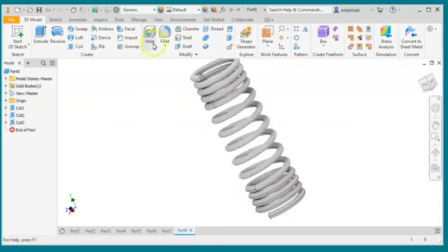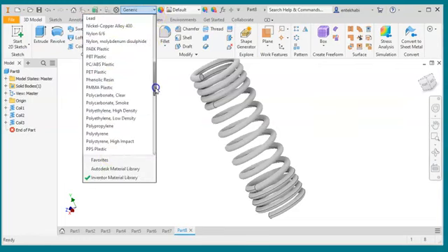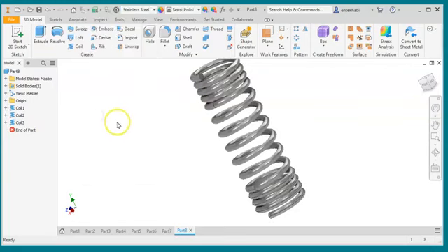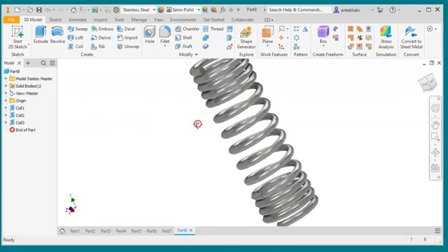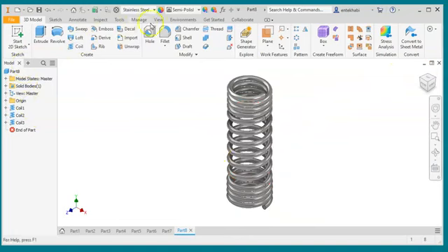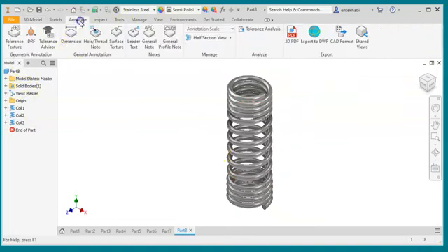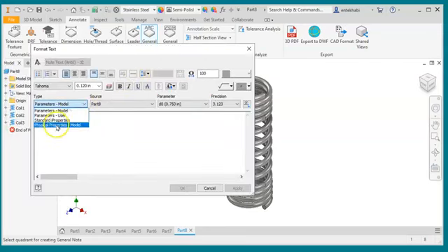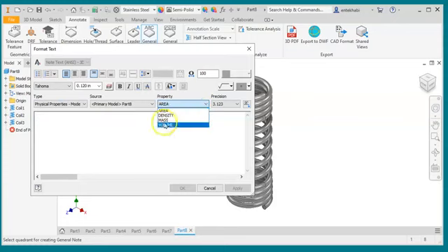The last thing is adding the material for the polished look. Let's go to steel. I believe I asked you to use stainless steel. Then, the last thing you would do is get the information under the annotation and add, to see what the information gives me here under the general note, and select the physical properties, mass.